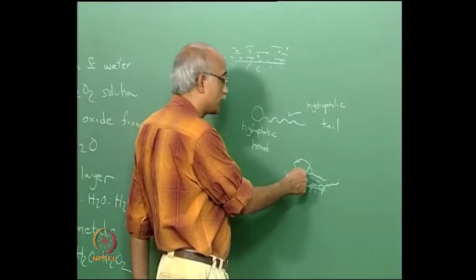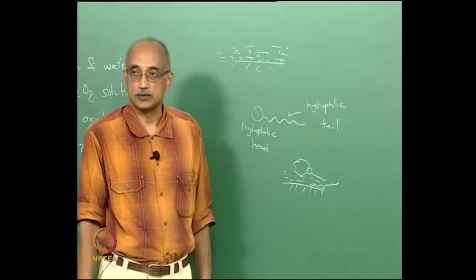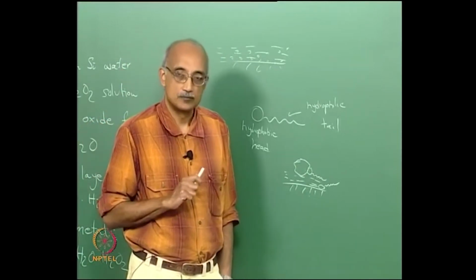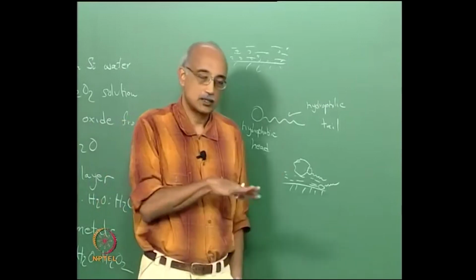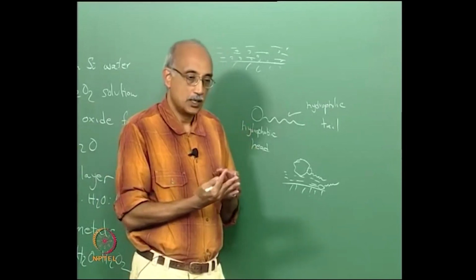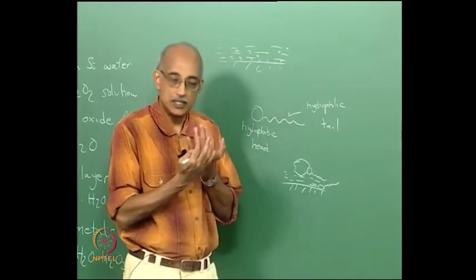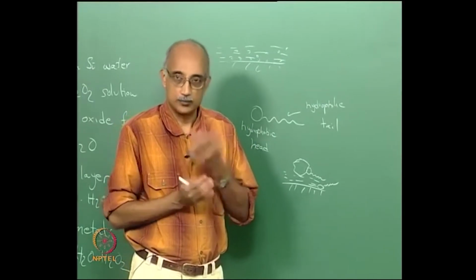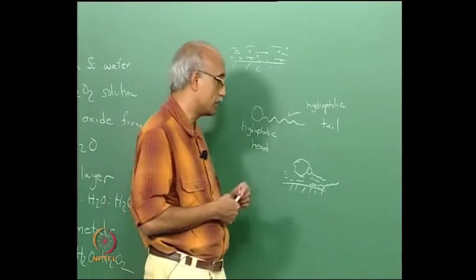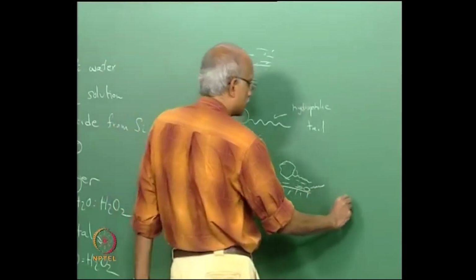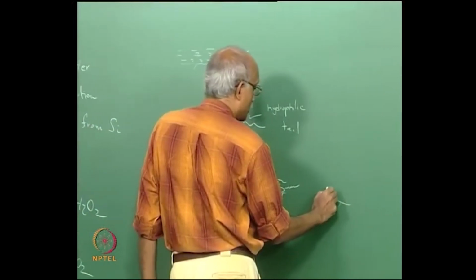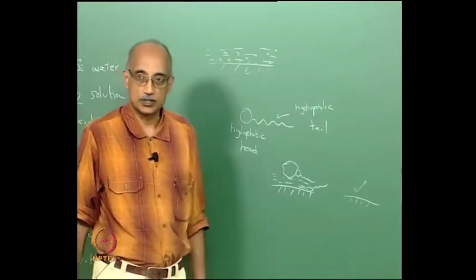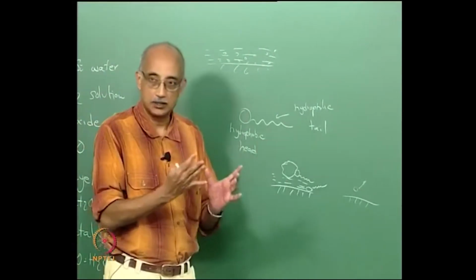So you set up a repulsion force between the particle and the surface, and that is really why detergents are supremely effective. They induce a state where the particle and the surface, instead of being naturally in adhesive contact, are now actively repelling each other, trying to push each other away. So as you can imagine, when this happens, the particles now are loosened from the surface and they actually have a tendency to move away from the surface and become entrained in the liquid.